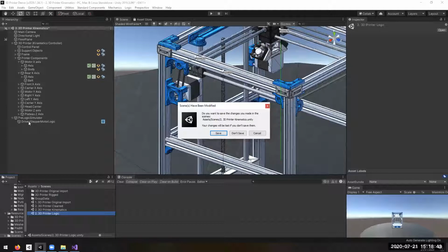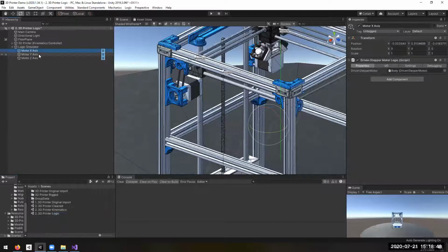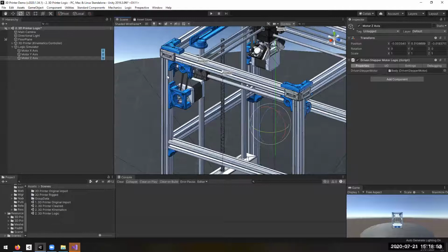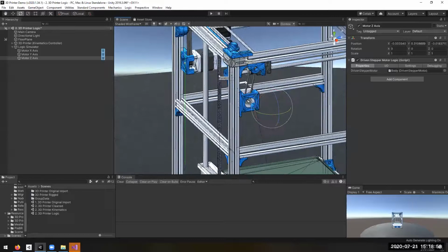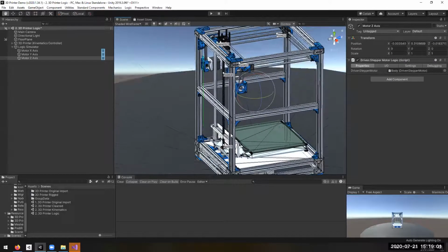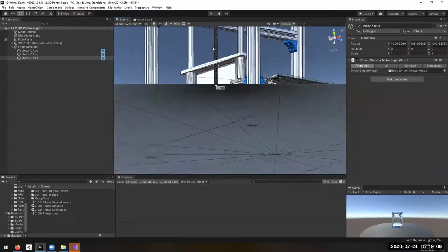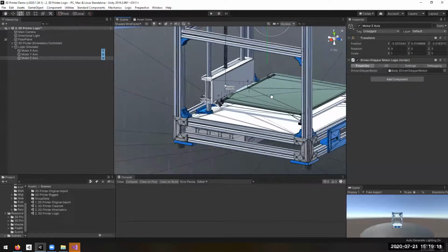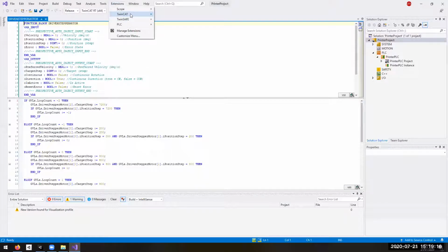So I have now only set up driven stepper motor here. And if I go back to our last scene, I have our 3 motors set up, which is this one for the x-axis. There is this one driving the y-axis of the printer, and there is one on the bottom here. There it is, which drives this worm wheel, which drives this plateau up and down, and that controls the z-axis of the printer. And let me activate this configuration.